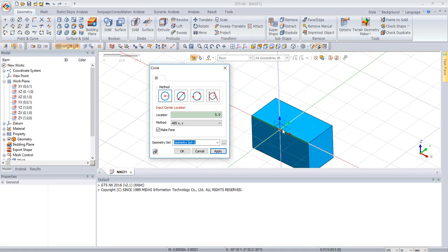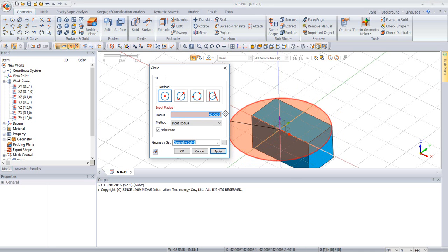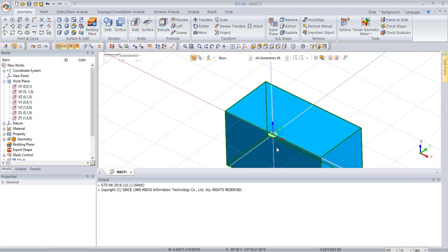And as far as location, I'm actually just going to put it at the origin, and then all I've got to do is give it a radius. And again, I can draw the radius. Obviously, it would be a little difficult because dimensions of this grid don't quite work for the dimensions of the project we're working. So I'm just going to tell it it's a 5-meter diameter pile, so the radius will be 2.5 meters. And so we see that there.